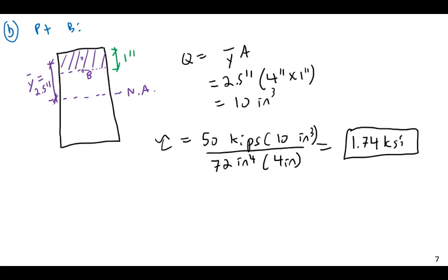There may be some weird exceptions to that rule. Maybe if we really dug into the math, we could contrive an example that didn't apply. But generally, if you have a normal shape, in almost all shapes, the shear stress will tend to decrease as you travel away from the neutral axis.